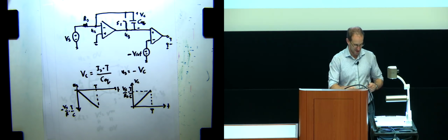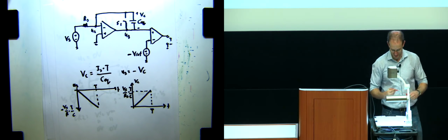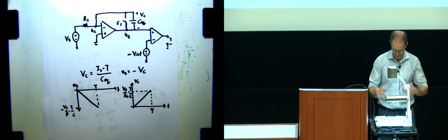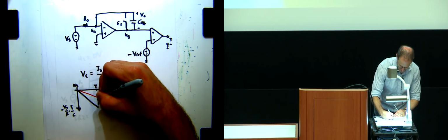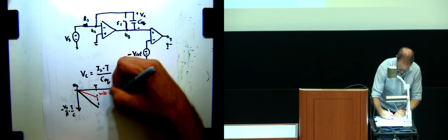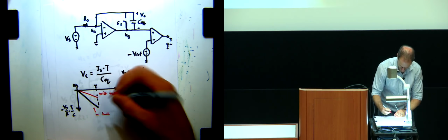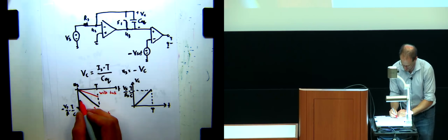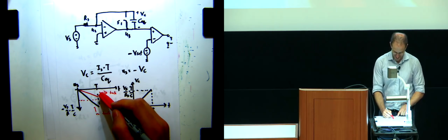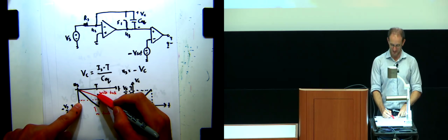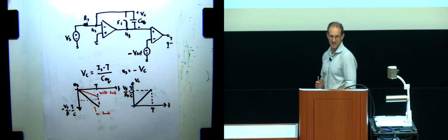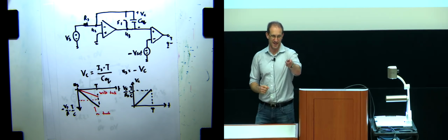To be clear, if I wanted to look at what happens when there is a touch versus there isn't, when there isn't, the value of the capacitance is smaller. When there is, the value of the capacitance is larger. So if this is with touch, and this is no touch, then what we're trying to do with that comparator circuit is put a minus Vref somewhere in the middle, so that if there is a touch, it will be above that minus Vref, and if there is not a touch, it'll be below that minus Vref. Everybody good with this?